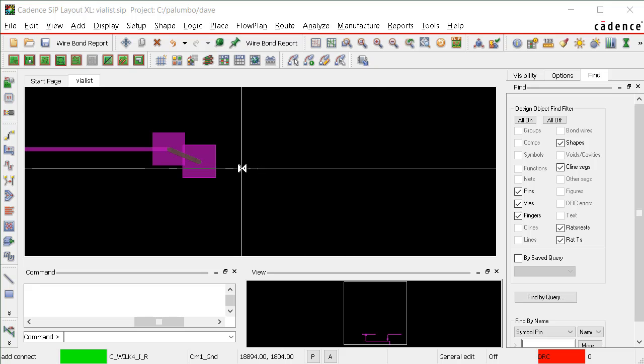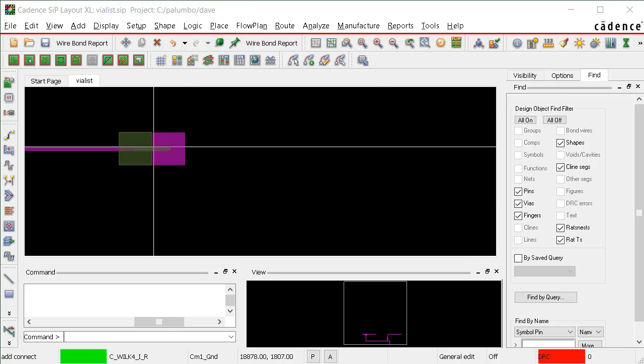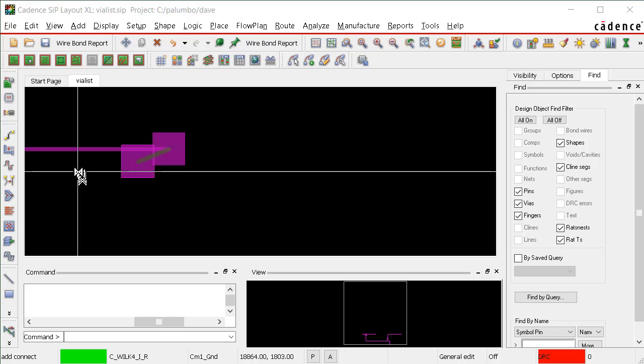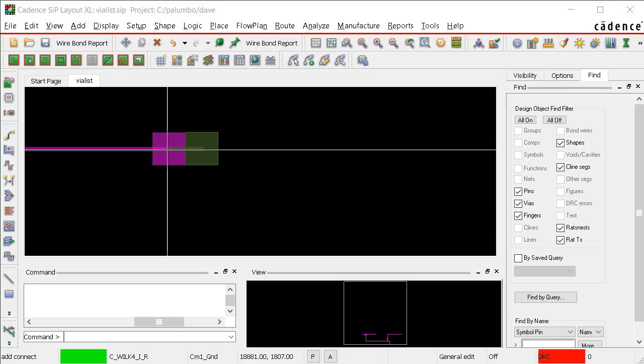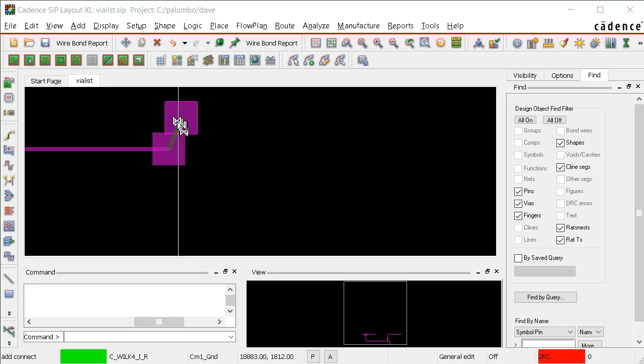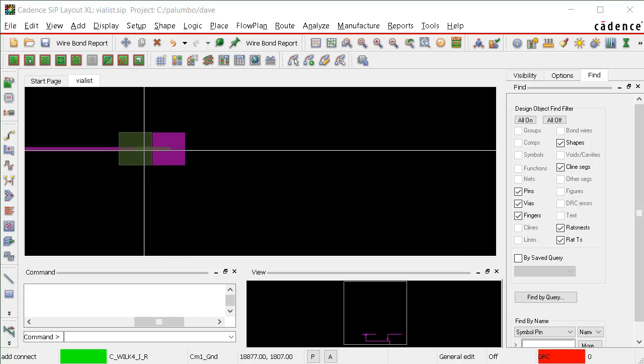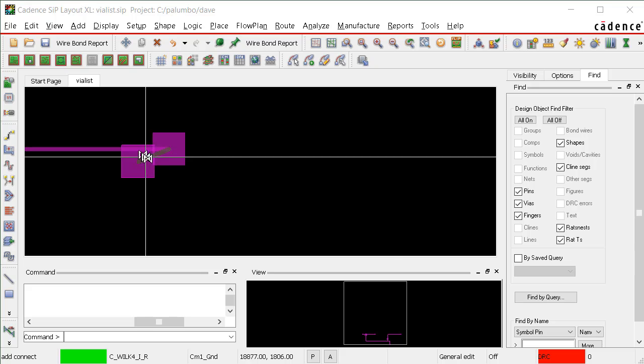And when we select CM2, our first via from the CM0 layer to the CM1 layer is added for us. And we notice that we get our exact stagger of 6 microns, so that when we line up our staggered second via, either horizontally or vertically, the two metal shapes are coincident, they touch.